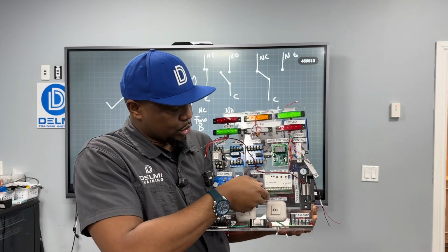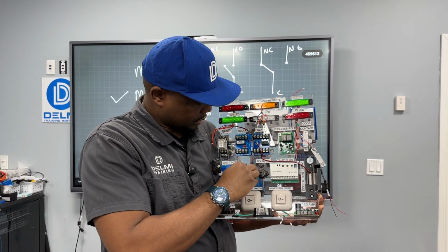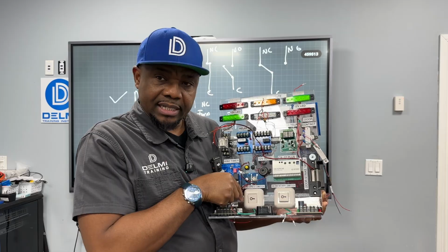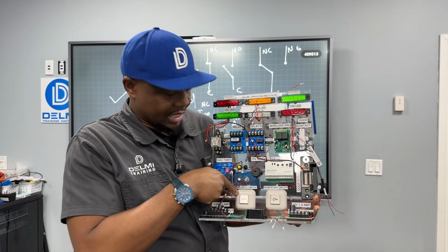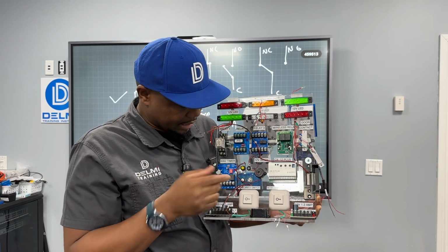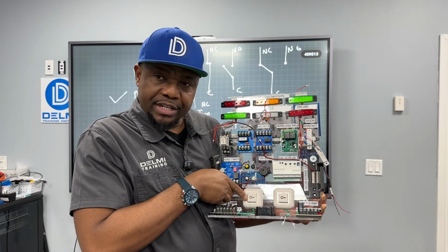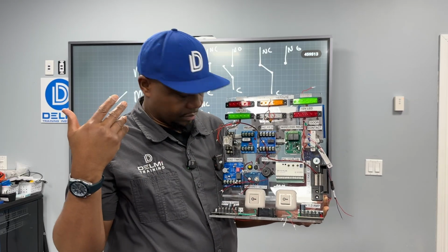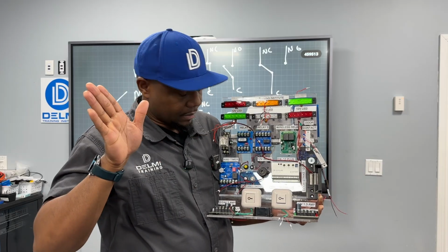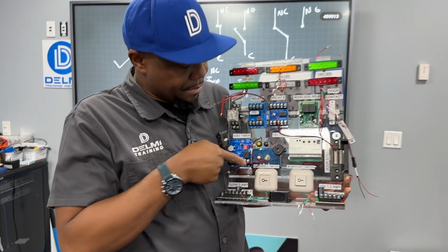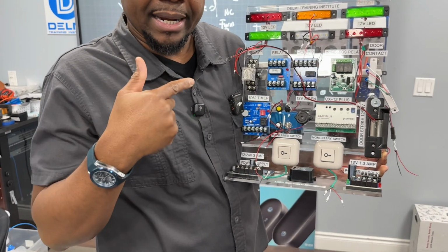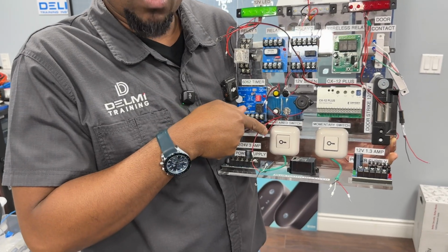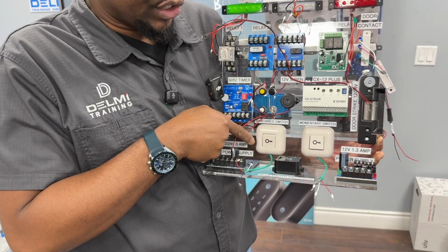When I look at these two switches, they are identical. Right, these two, they're very much identical. One of them, look at the first one here. When I press it, it's going to stay. It's going to stay in that state, and it's going to forever remain like this until I come back and I change it. So this is what we call a maintained switch.